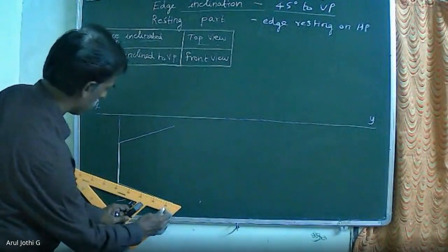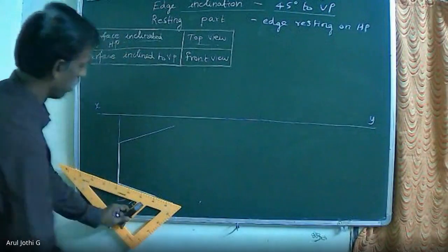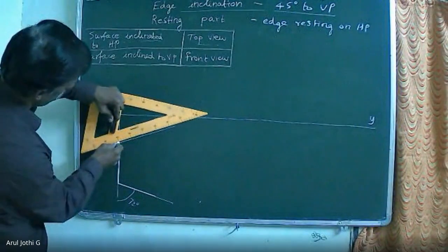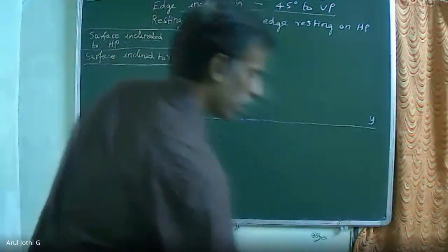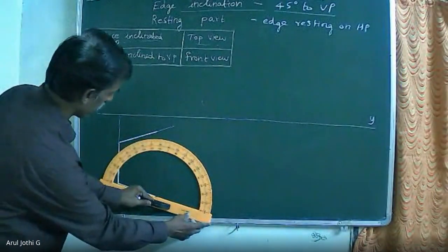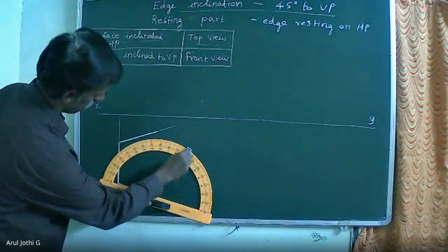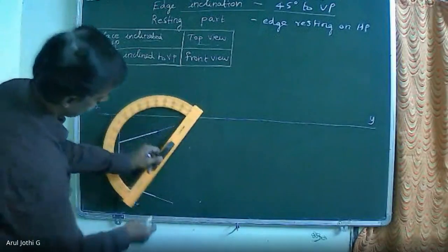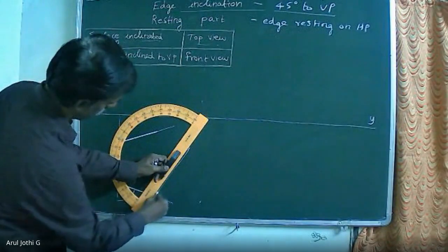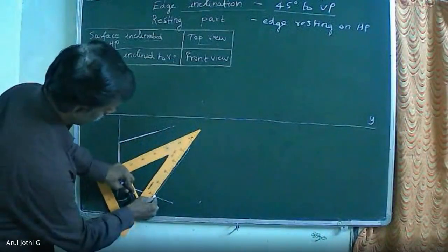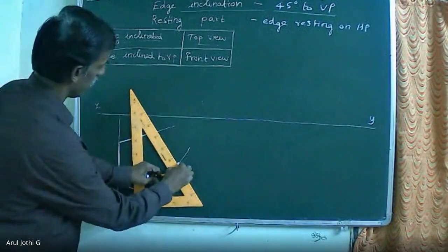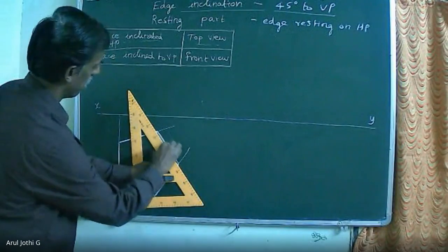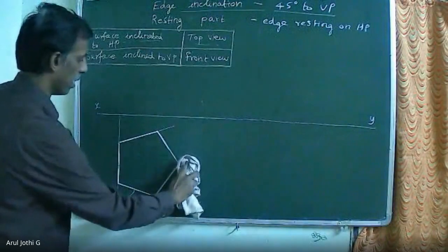Now we keep 30 mm. Similarly here on this line. I keep the protractor here. 0 will be here. So 72 degree. Draw a 72-degree line. So on this line, take 30 mm. Base side is given as 30 mm. On this line, you have to draw the 30 mm line. So now you can close the pentagon. After that, you can erase the extra lines available here.